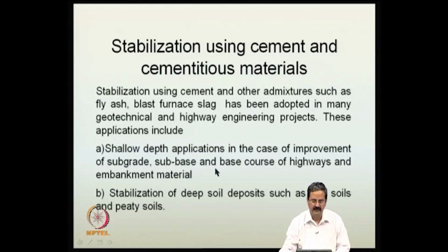As we have seen earlier, we used lime to increase the CBR and to increase the stiffness and all that. Here we can use cement as well, because many of the industry people are more comfortable with cement, though it is going to be quite expensive in many of the projects. But people have been comfortable with the use of cement, and particularly right from the 70s, a lot of work has been done on the use of cement as a stabilizer or as a modifier in ground improvement.